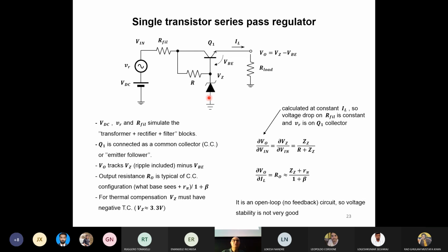This is not something so difficult to happen, because if I'm using this for a power supply, maybe here I want 1 ampere of current at least. I'm using this transistor here, but for transistors which are able to manage 1 or more amps, the beta is much lower, around 20 to 50.